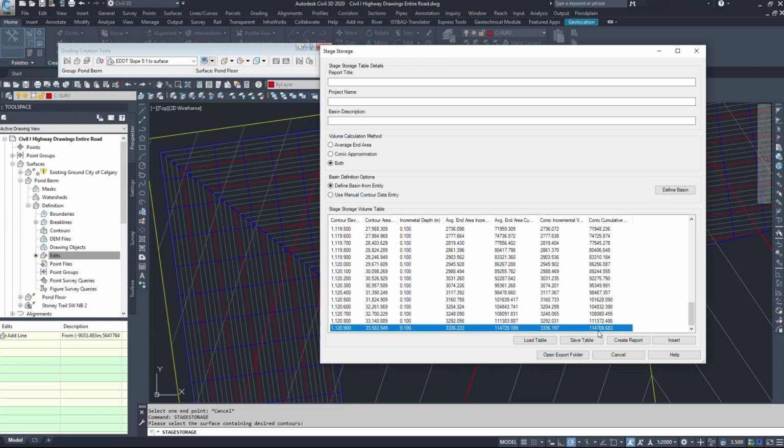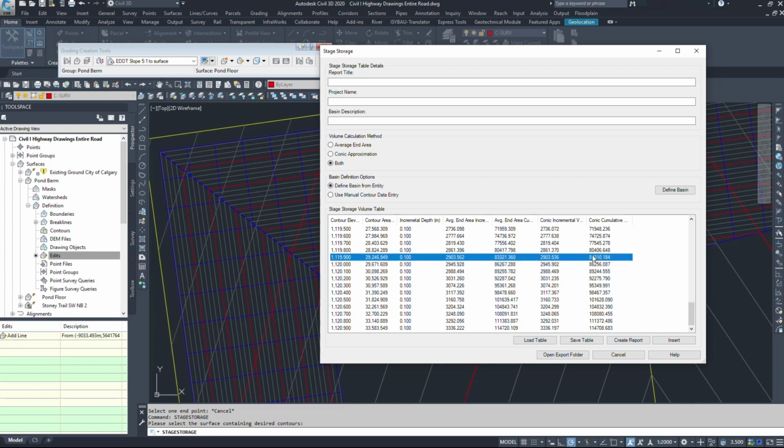Now at the very top of my pond, I am holding 114,708 cubic meters of water, whereas if you remember back, I need a mere 83,000 cubic meters of water. Now, like I said, we don't want to fill the entire pond up, but we also don't want to have a berm that's giant and massive between the elevation of the water and the elevation of the top of the berm. In this case, mine is about a meter difference here, where we want to go about, we'll say half a meter, so 500 millimeters. So I want my top of berm to actually be around 1112.4.